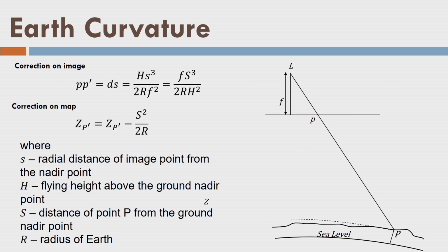Let us look into the correction for earth curvature. Now, if you are using a GPS or any system which is taking care of earth curvature, this correction need not be applied. However, when we do not have the GPS with us, we used to do pseudo 3D survey, where we used to say that we are measuring the heights with respect to the mean sea level, which is a Earth's equipotential surface, and these heights are superimposed on a map plane in order to indicate the height of a point. The heights are perpendicular to the mean sea level, not the map, and this is done here.